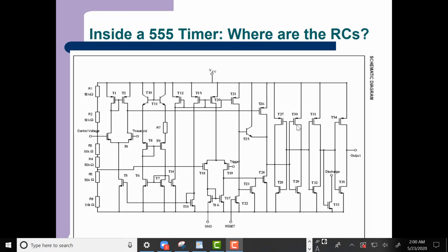But once you have that equation for where a zero is, it's kind of like when you have r_pi, r_pi equals beta V_T over I_C. You know the equation for r_pi, so you don't need to recalculate it every time you need to figure out the value of r_pi. Same thing for zeros. Once you do that small signal analysis and figure out the equation for where the zero is, you can just use that equation and you don't need to recalculate every time.